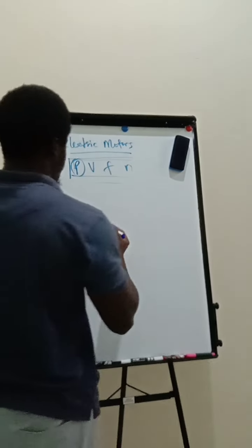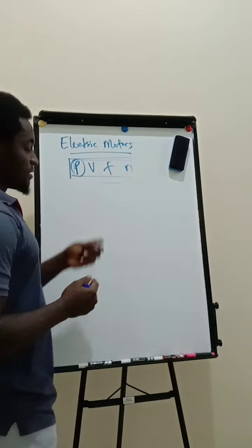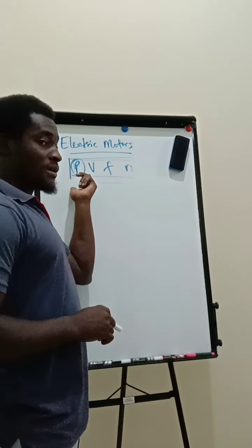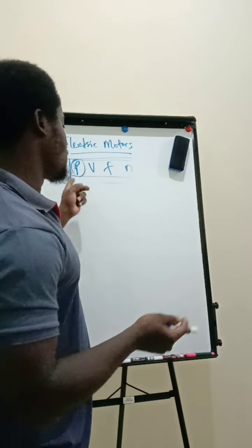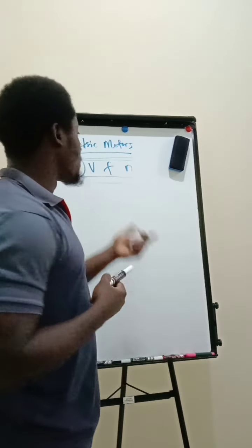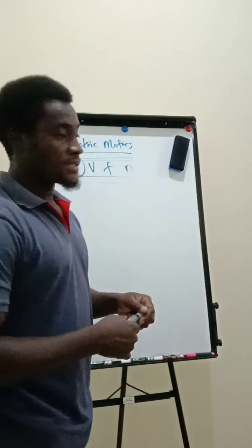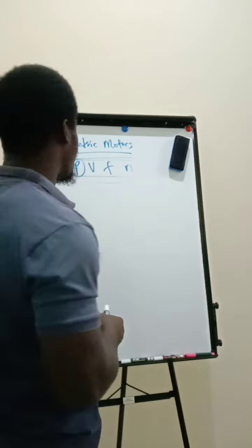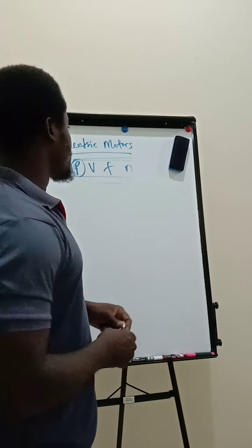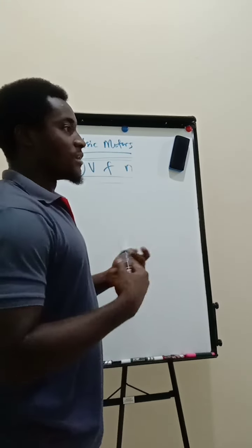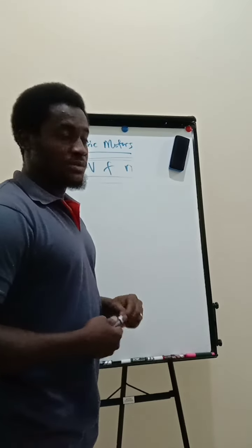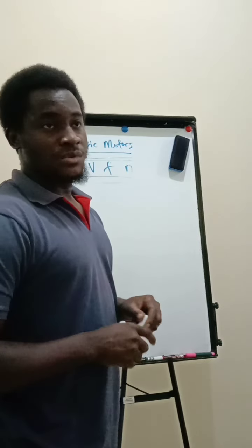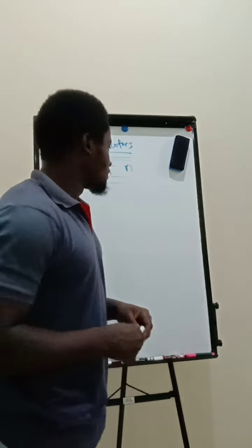So after taking down all the different parameters, we'll be able to know the power of our electric motor. If it is greater than 11 kilowatts, we will employ the starting method of star delta starter. If it is less than that, we operate it using a direct online starter. It's very important to understand. When we are supplying power to the electric motor, we should know the particular starting method to be used for that electric motor to serve the application.